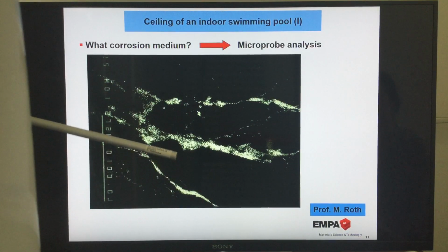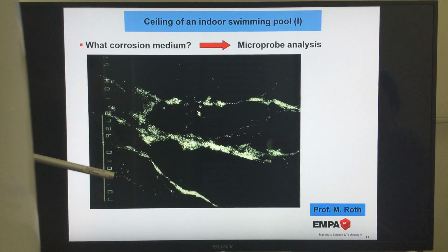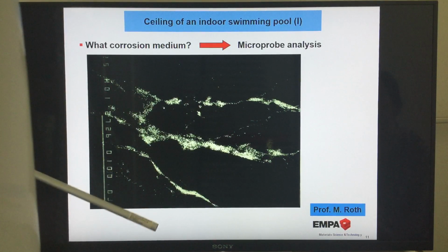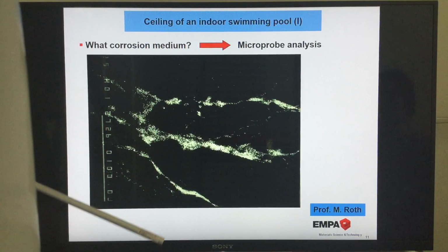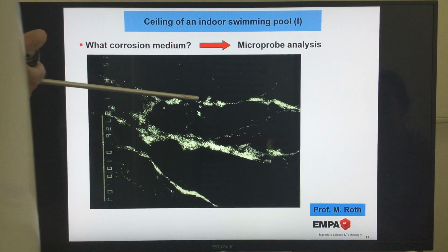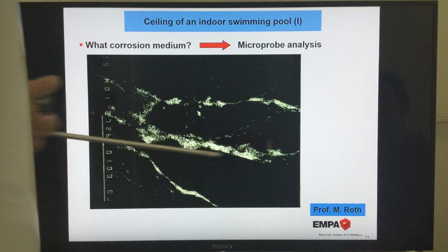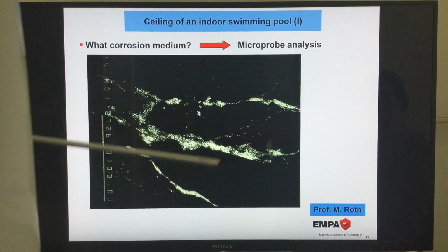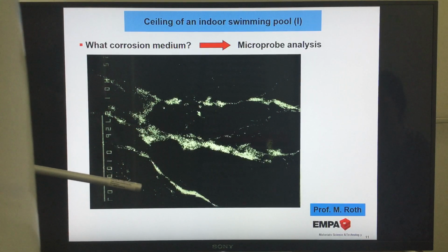It's iron positively loaded. So we need, for compensation of these positive loads, negative loads, and chlorine is negatively loaded. That means the chlorine will be pushed all the time, following inside the crack to the crack tip. It's a continuous process to be at the crack tip. That is a very important process. Keep in mind that.